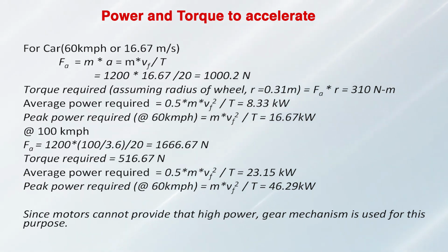516 Newton meter, and the average power required will be 23.5 kilowatt and the peak power is 46 kilowatt. Since motors cannot provide this high power, a gear mechanism is used for this purpose.